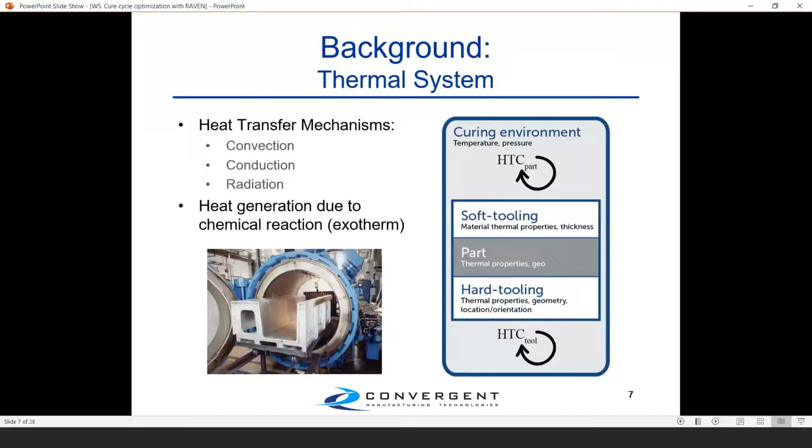And so one way to incorporate that is actually to artificially thicken the tooling thickness there, and it would be an equivalent thickness to the thermal mass of that understructure. It's particularly applicable for metal tools because they have good conduction, and typically good conduction between these. The surface composite tools might be less of an issue.